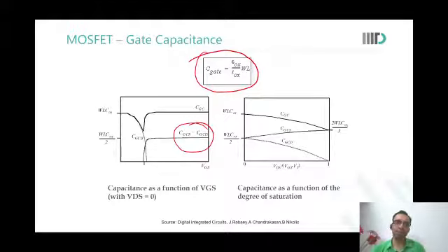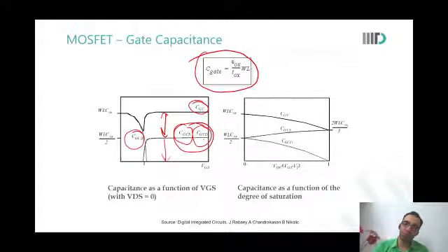There are various components. This is capacitance with bulk. This is capacitance with source. This is capacitance with drain. It's saying that all three components add up to form CGC, the gate capacitance. And source and drain have equal coupling because of equal overlap and equal density of charges there. Therefore, overall CGC is double of CGS and CGD.